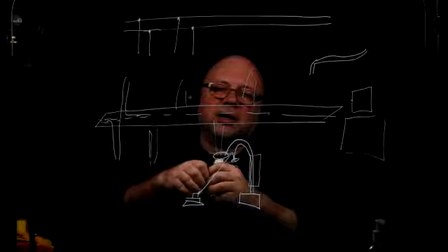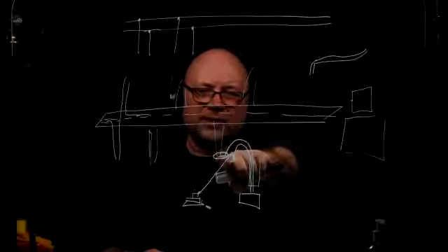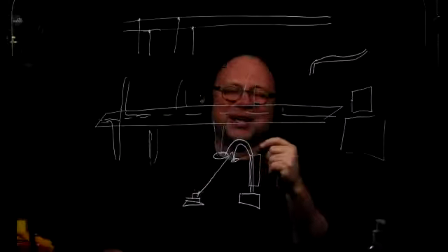So cutting it, stripping, and getting ready those pigtails that are going to the volume control, if we're using a volume control, because sometimes we don't. Sometimes we just mount the speakers. We don't need volume control for every speaker if it's in the hallway. But if it's a bunch of speakers in the hallway and you just need that one in the office somewhere, then you're going to have to do it that way, right? So we're just going to do it that way for every speaker.